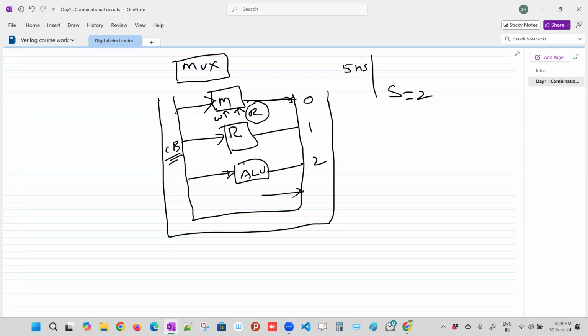So it also has some controls. Depending upon that, the bus is occupied with the memory contents, MC. This memory content can go to the ALU, can go to the registers, or can go to other units also. That is managed through the control signals that are there with every module like this. The muxes play the role of controlling the common bus.